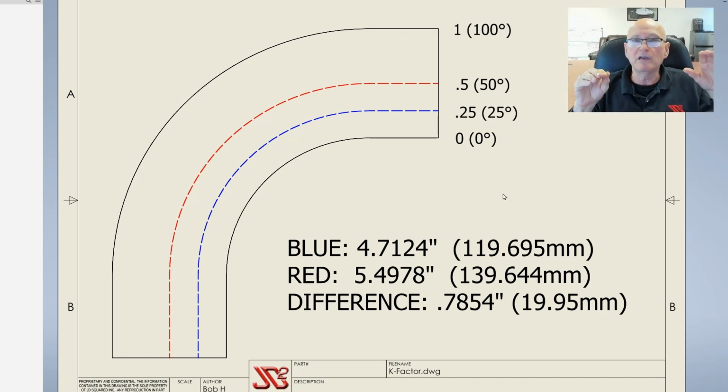So what you're going to be looking for as you move through your fabricating process over the years is you're going to fine tune your bend radius and your K-factor until you're happy with the results. Do not expect perfection. Always add. A good engineer understands there are tolerances in this world and we have to obey those tolerances. So keep that in mind.